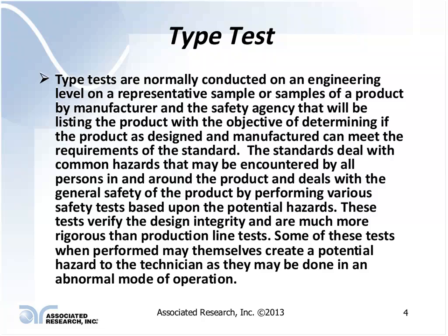Is it meant for outdoor applications versus indoor applications? The pollution degree. What kind of environment is the product submitted to? If it's got a fan in it, will that fan ingest a bunch of pollutants into the product that could decrease creepage and clearance distances that could create a shock hazard?